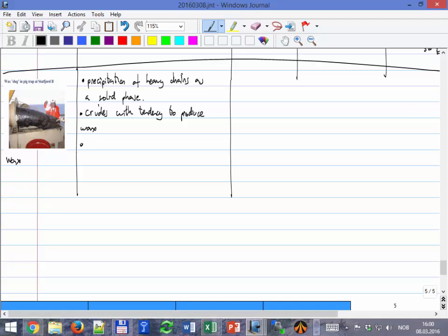Okay, and there is actually the same way the hydrates have, a P&T combination that defines a region where I will have wax formation and non-wax formation. So there is also a kind of thermodynamic equilibrium of wax playing a role, for a given P&T.